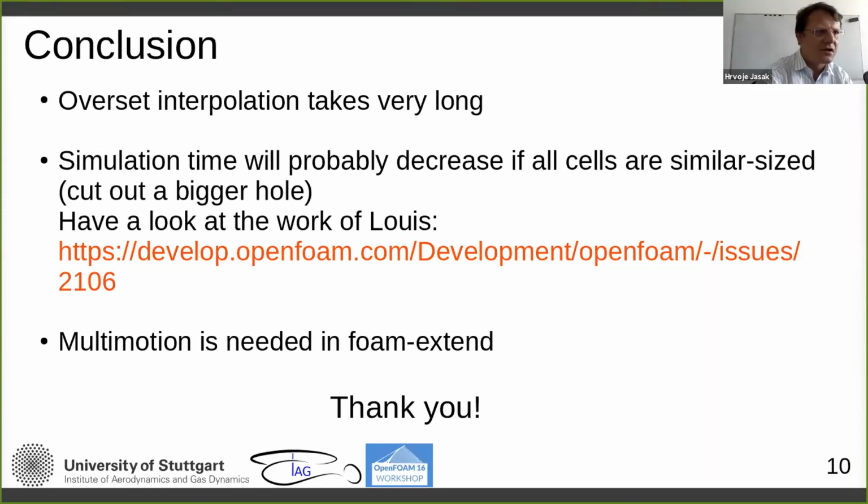Joseph Naj is asking about the pressure oscillations. Did you check the convergence within a time step, and how many nCorrectors and nOuterCorrectors did you use? Because sometimes that can make a difference. Yes, for this situation, I use 3 nOuterCorrectors. But maybe I have to play around. Maybe this can be resolved by making the case a little bit better. So thank you very much for the tip.